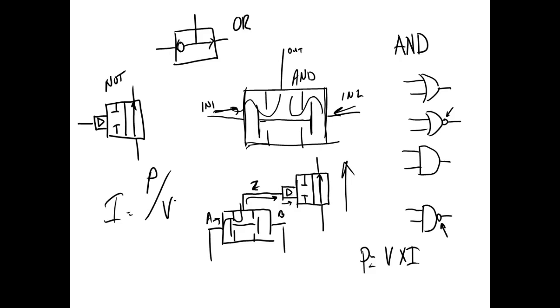You'll hear people say that all the time: 240 is more efficient. No, 240 is not more efficient. You're paying for watts, right? But now instead of running 4-gauge wire back here, I can run 12-gauge wire, and run that load. Now I can run that wire through the beams of my house without running it through the ground. I can pull that wire now. So the higher the voltage, the cheaper it is to install and maintain.